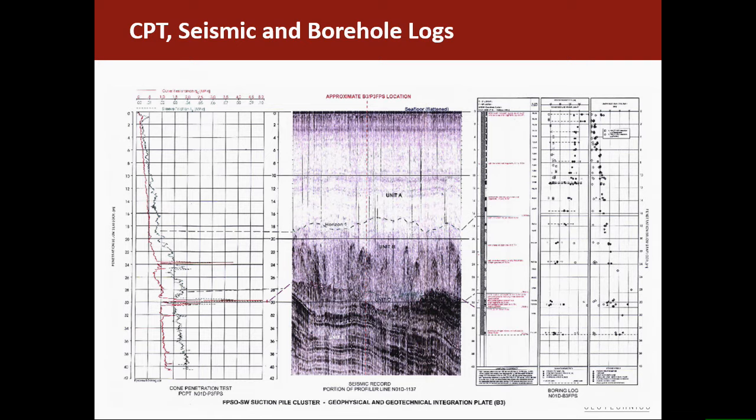It was very soft clay. The moisture content was close to the liquid limit, in some cases actually greater than the liquid limit. And their undrained shear strength test, so that's the undrained shear strength there. That's a remoulded strength, the empty ones are remoulded samples. 2 soil units were picked up from that horizon.